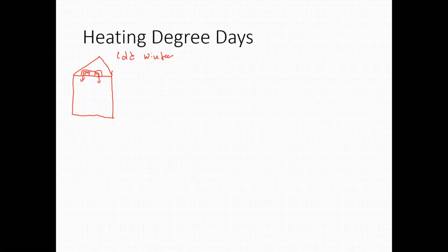So you've got your heater in your attic, it's pumping warm air. You want it to be about 68 degrees Fahrenheit inside your house, right? So we have this thing called the balance point. The heater is going to kick on at some temperature outside to keep your house at 68 degrees. When it's cold outside, we're losing heat through the envelope.